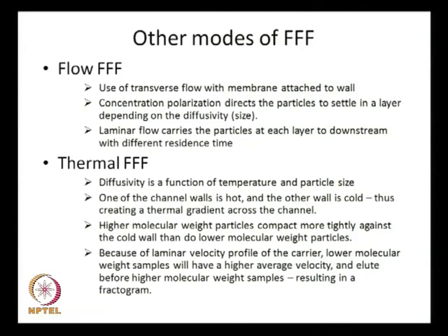Now, I said that this field flow fractionation is a very unique treatment, where layers are moving, sliding one against the other, and we are relying on it. We are assuming that if there is a cross flow, if some eddies are forming, then this whole idea you should throw in the dustbin. It is absolutely of no use. You are relying in a very significant way on the flow of two layers parallel to each other, and only diffusion can take place between the two layers, while one layer is sliding against the other.